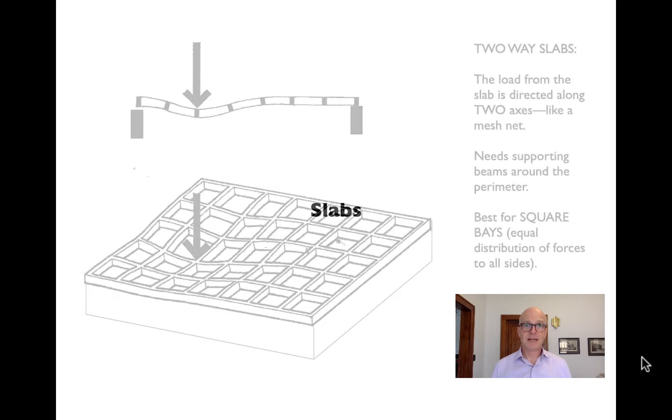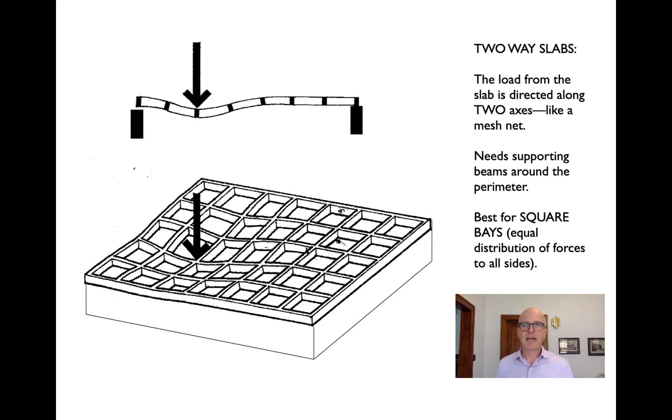So to start with slabs, the first thing we look at, and remember that when we're talking about slabs, we're hoping that we can make them perform like two-way systems. So redundancy in load paths, loads that are transferring in more than one direction, that therefore allow us to take advantage of this synergy of the two axes. If we're resisting deflection in two axes, we're getting an exponentially greater resistance to bending.